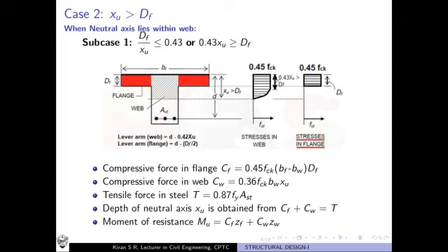Okay, and now this rectangular portion I am calling by the name web, although the web is actually the region below the slab. For the time being, I am calling this rectangular portion the web, and these outstanding portions I call the flange. Okay, for the time being. Now you see I am drawing the stress distribution for the web as well as for the flange. And for the web, this is a typical singly reinforced beam, and you know the stress distribution which we have already learned.